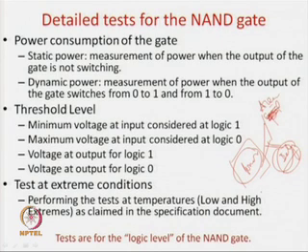Also, you might have heard that we sometimes say that our processor, like an Atom processor, is a very low power processor or it consumes low power. So, you also have to find out the power required by your AND gate. If your AND gate is very fast and functionally very fine, but it takes a lot of power, that may not be good for your design. So, along with this delay test, you also have to go for a power consumption test.